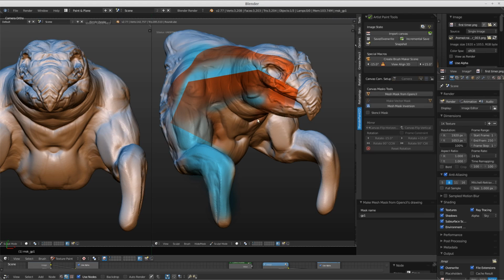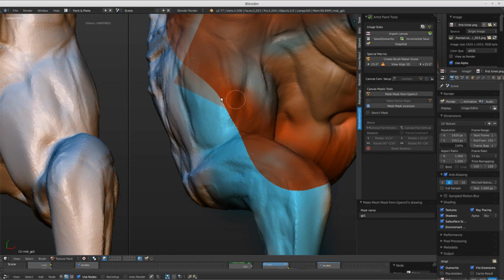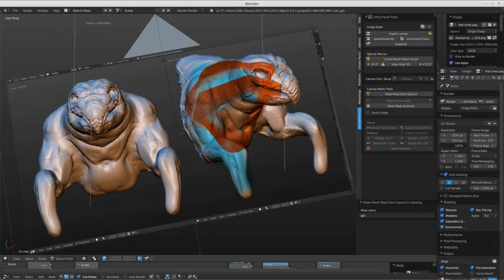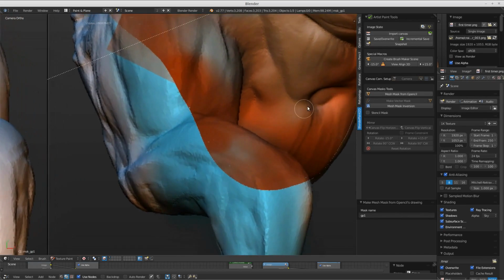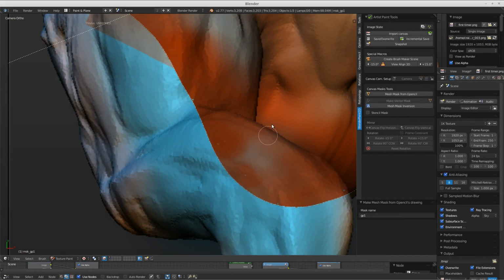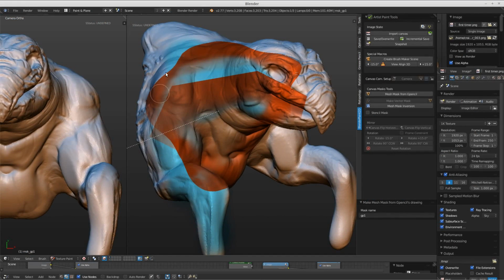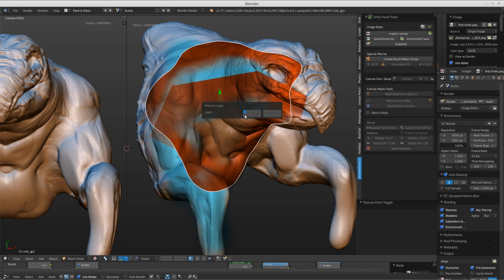And here you go. With very odd shapes, the grease pencil has to create so many little triangles to work. Because of that, those triangles will sometimes cause projection problems because they're so small. We'll need to make sure that we've got a close-up to get it to where it works, and you might actually be better off, once you've got the bulk of it done, coming in and cleaning it up after the mask is gone, when you're dealing with just the solid plane. Okay, like that, we're going to go to object mode, move it to another channel.